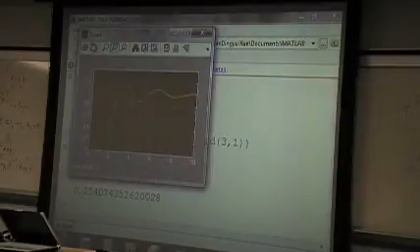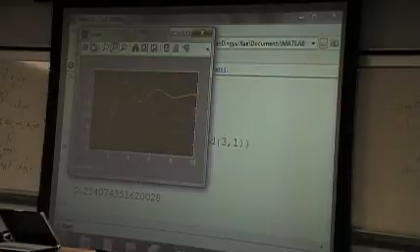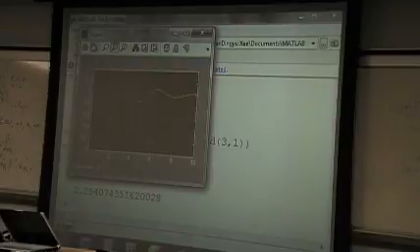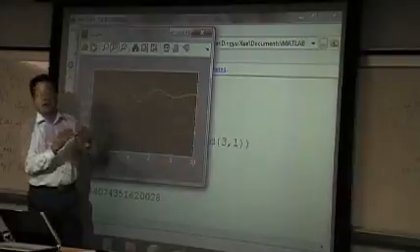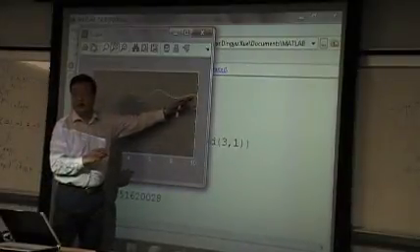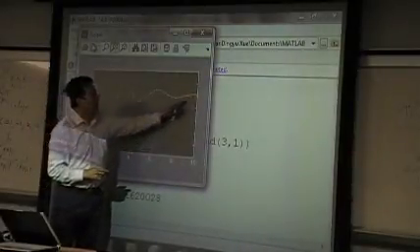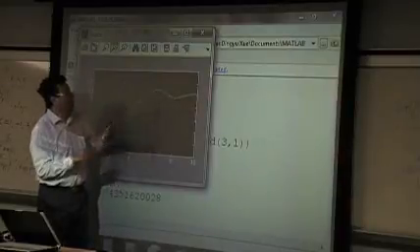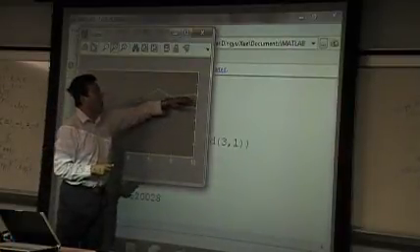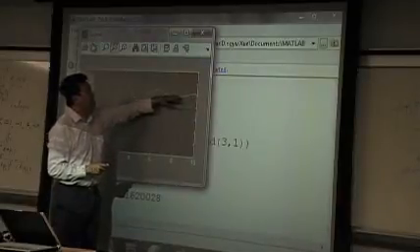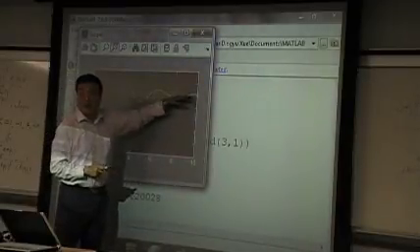However, with the ITAE criterion, where we use time t, when t is large, the weighting is large. We multiply t with the error. So when the weighting function is large, it will force the response to make the error close to zero as soon as possible.